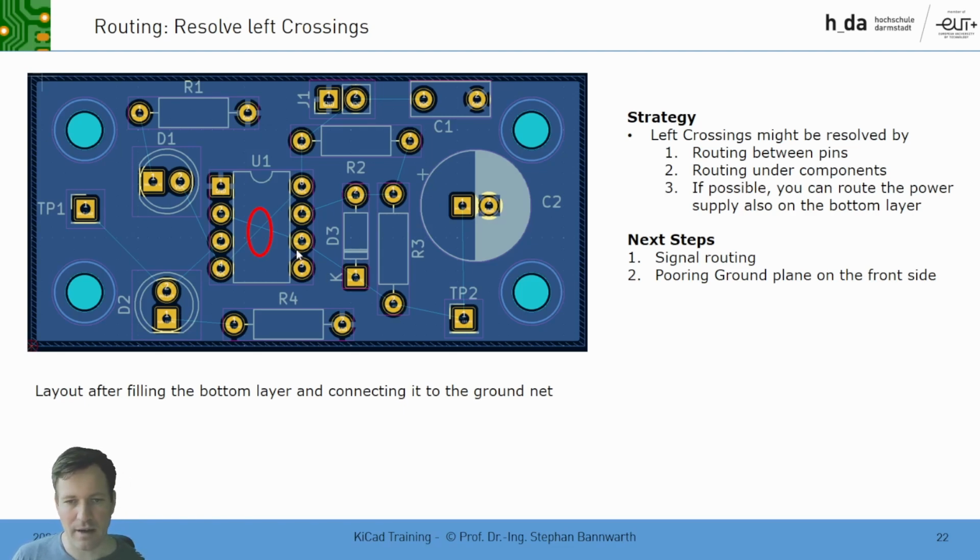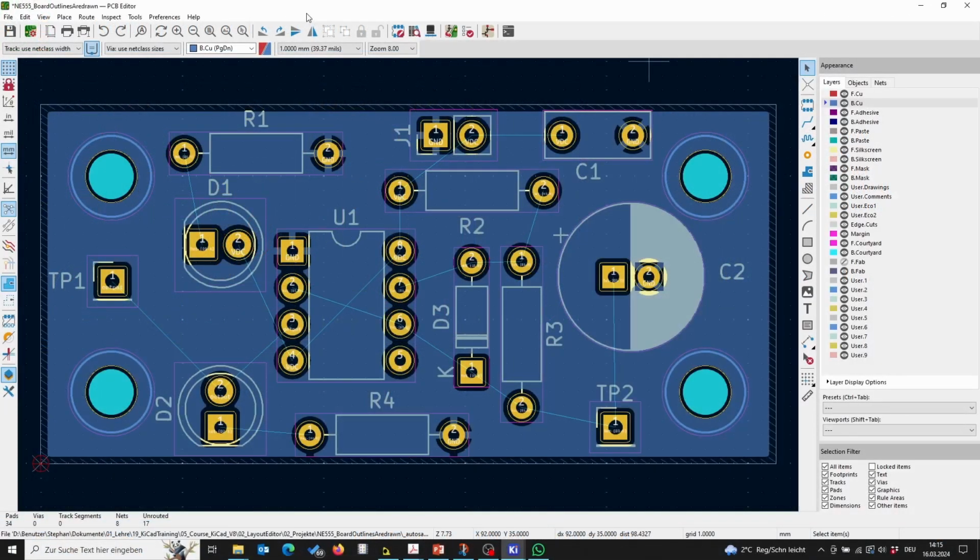That's the one thing. And electrically, it's nice to have the copper everywhere because you can have shielding for the signals around you. Okay, let's go and finish our PCB. As said, let's start with resolving the crossing here of the connection from pin 4 to 8 of VDC and pin 2 to 6.